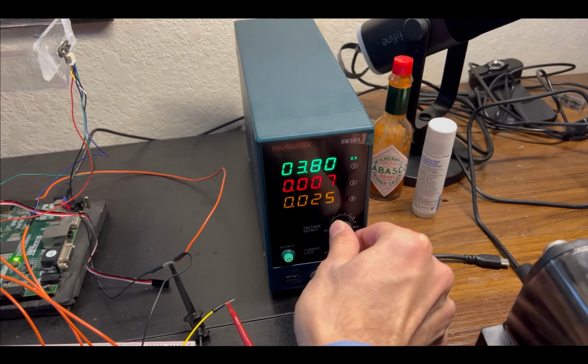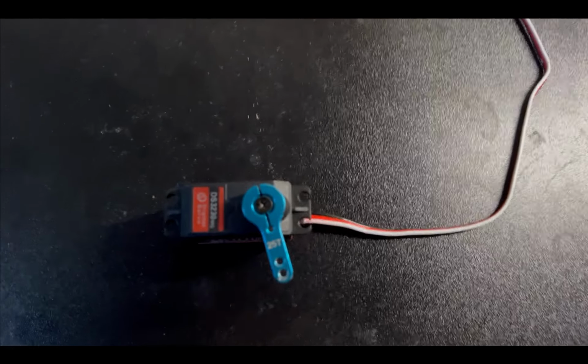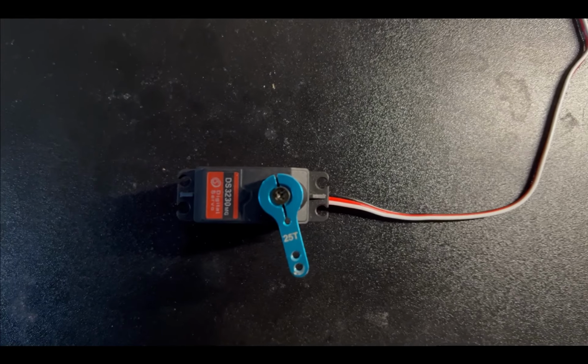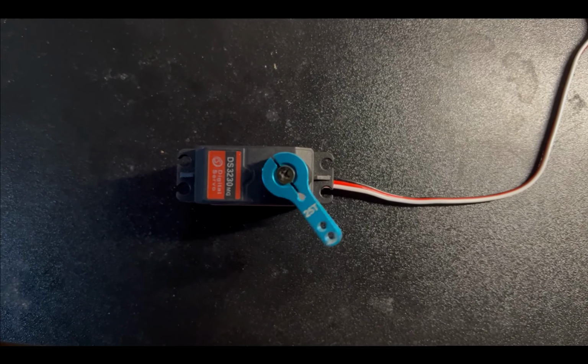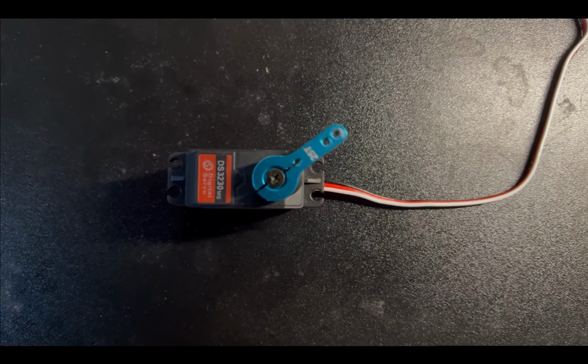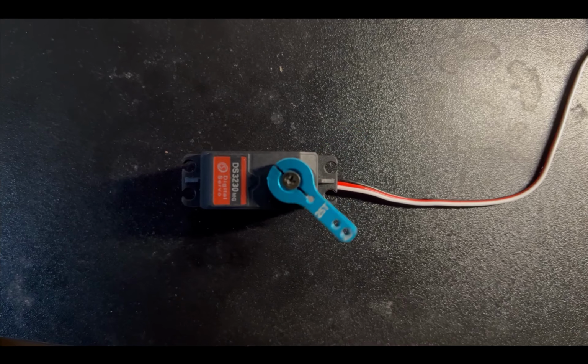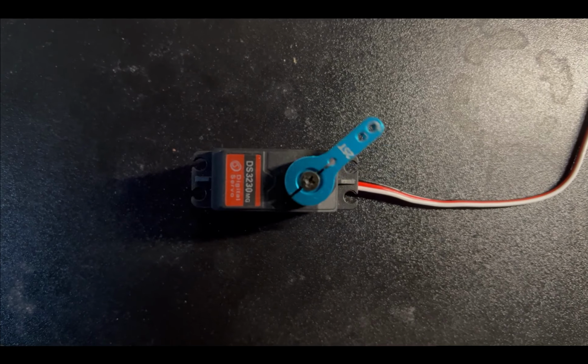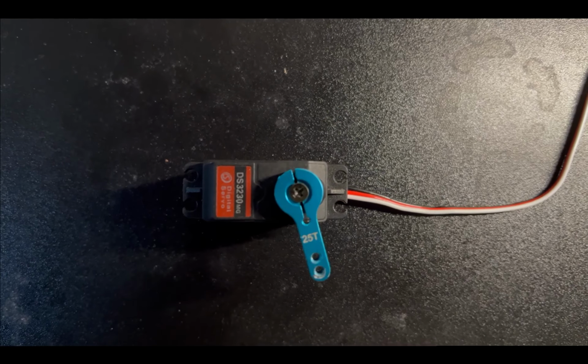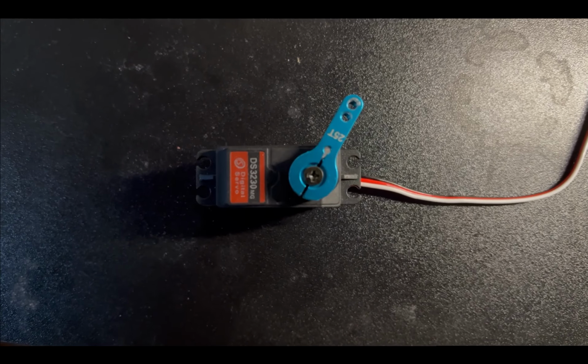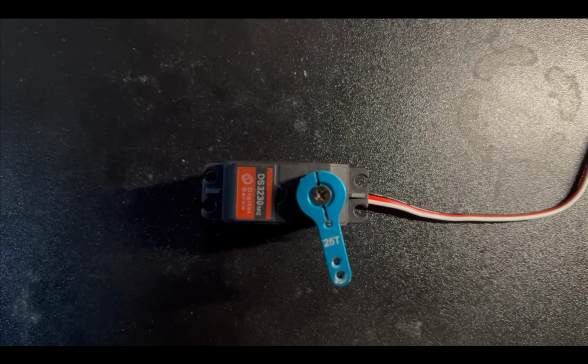There are two main ways to increase the servo speed. The first is to power the servo at 5 volts, which increases its speed according to the datasheet. As you can clearly see, when we power the servo at 5 volts, it moves much faster. While using more voltage speeds up our current servo, the better solution is to use a more expensive servo that is much faster.